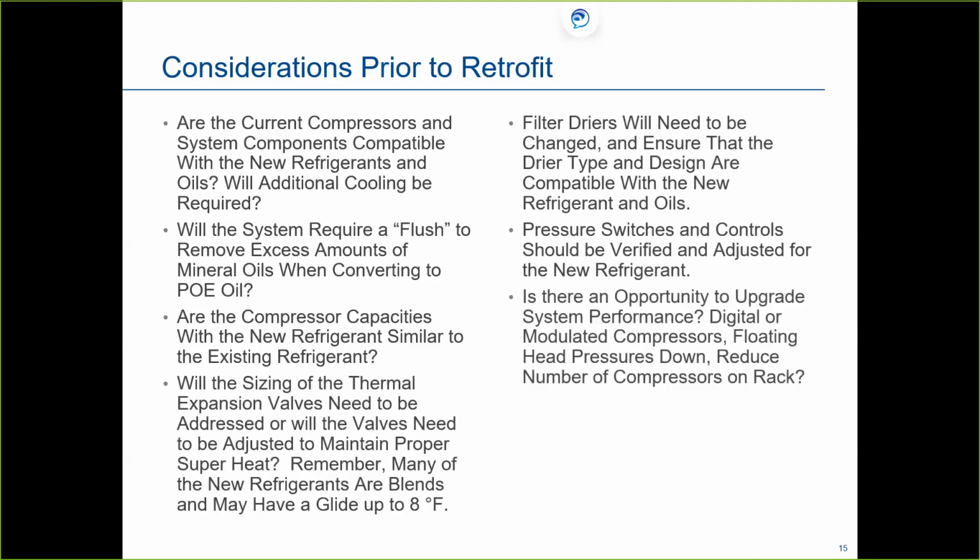A lot of people use the phrase drop-in refrigerants. I don't know if I really like the term drop-in refrigerant. That always is kind of misleading. I know when I was in the field, when I first heard the term drop-in refrigerant, it seems like you can just take the new refrigerant and drop it in. That's not necessarily what it's saying. It's saying maybe that it's more like the old one in the pressure-temperature relationship. But you still might have to have components changed out, okay? Be very aware of that.